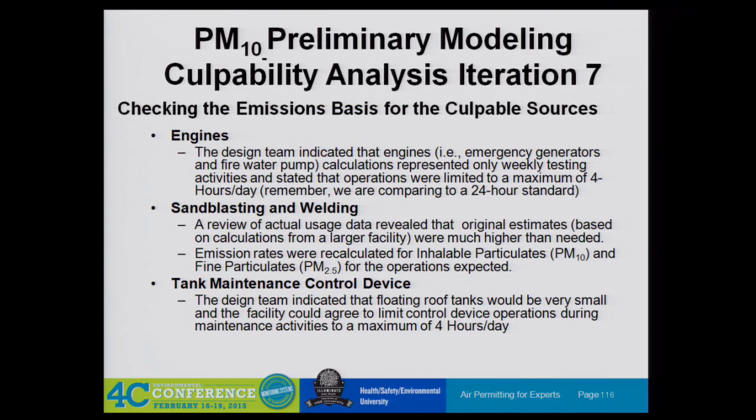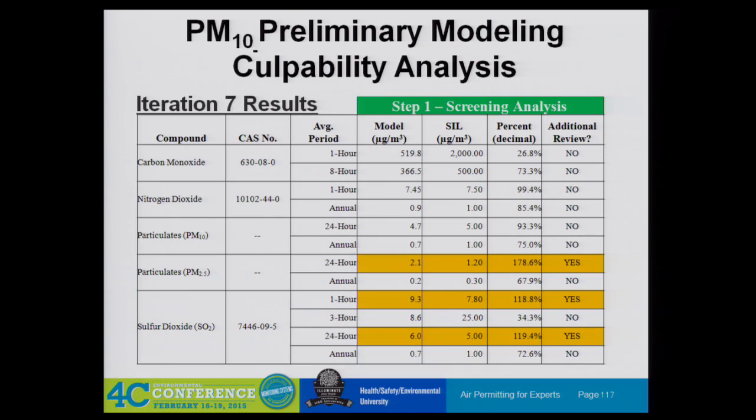All these little things were couplable sources, but when we applied that 24-hour average, because this is a 24-hour standard, right, for PM10, when we adjusted those emission rates from a pound per hour rate to a pound per 24-hour rate and remodeled, basically we got there. Okay?